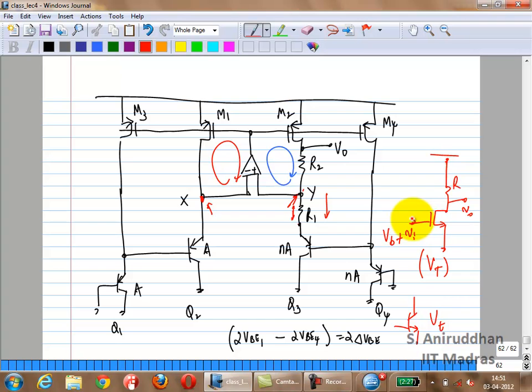Okay, why would it decrease? There are many factors. The current equation is very easy to write. First of all, what all factors change? Threshold voltage. What else? Mobility. Anything else? That's it, actually. The current equation doesn't have too many unknowns. So mobility and VT.